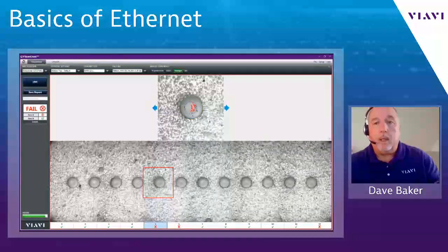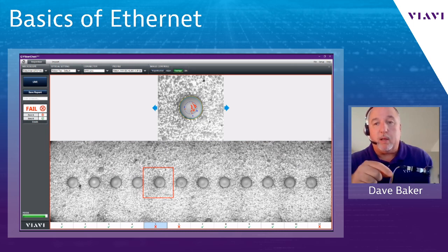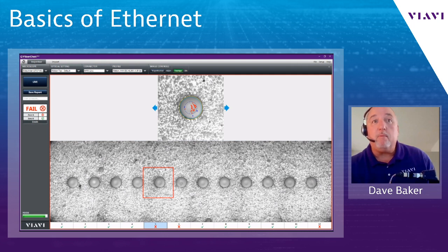Thank you, Peter. Now I have a fiber inspection microscope here for MPO connectors. We look at the base of it. I have an MPO connected. I've already tested this MPO cable, and you'll notice it failed. There are several fibers in this MPO that are fine, but there are also several fibers that failed. The summary at the bottom here. So if I were to connect this up to my network, I would risk damaging the equipment. I would also, in best case, have a reduced signal level and perhaps not be able to pick up the signal in order for an SFP or optical equipment to recognize it, and I'd end up with a high error rate on the network.